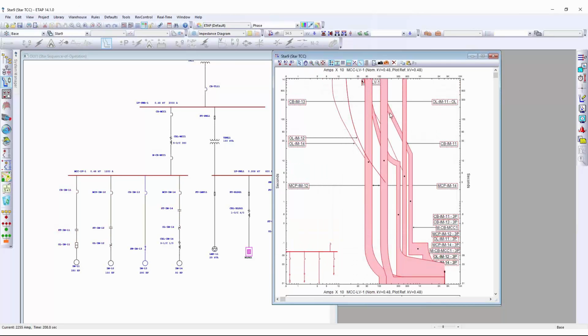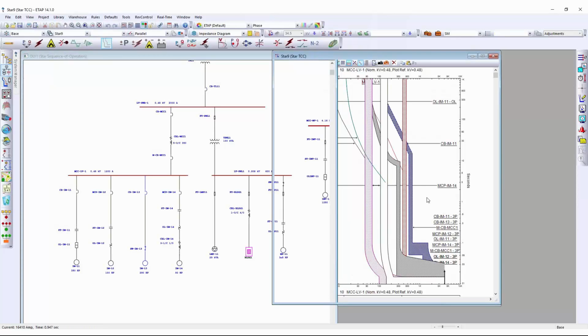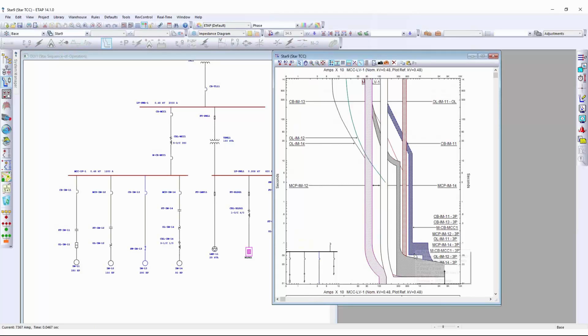we said you have to do one by one, but still you need to switch between them and remember what you have done between all, and make sure you have noted or documented your changes as you move upstream or moving forward. So this is a traditional procedure for doing the protection and coordination studies. For coordination, as we said, you need to apply the time margin between the upstream and downstream devices, depending on if they have a ban or don't have a ban.